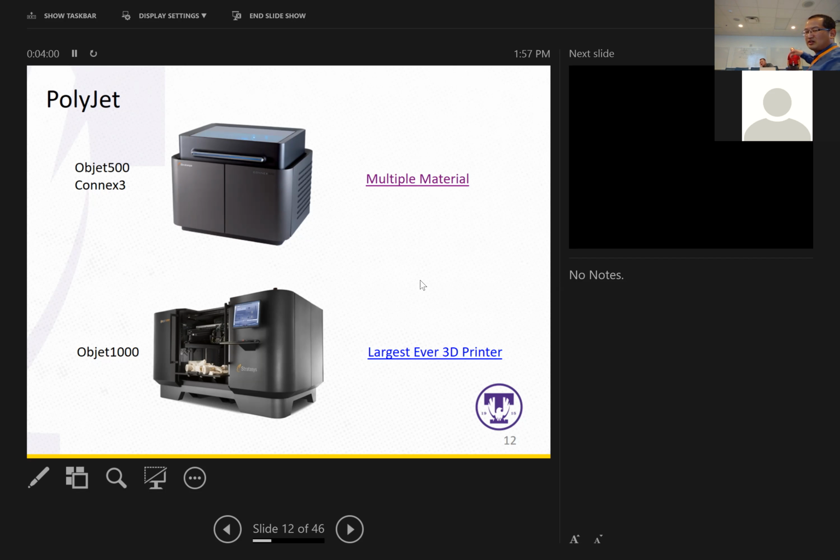Well, that limits a lot of things. But for the glasses, definitely nylon could be one material. I'm not sure whether this can do nylon or not. I know some of the FDM machines can do nylon successfully, and also the jetting, binder jetting, they can do nylon, but I don't know whether this PolyJet can do it.